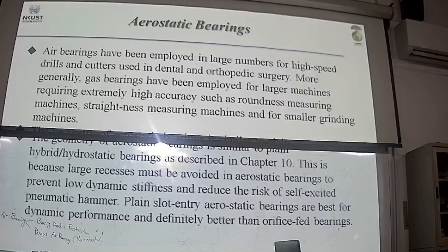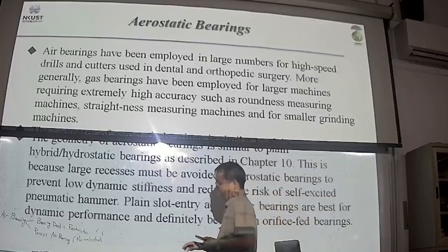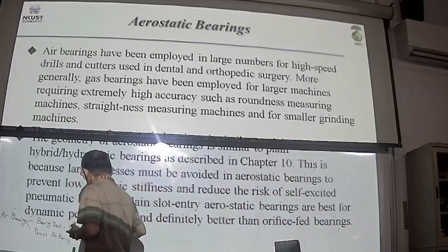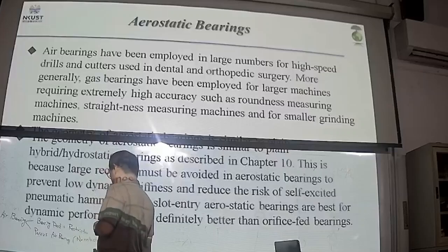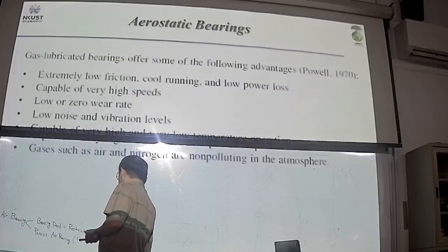And for the air bearing we discuss here, we always discuss the bearing pad design plus the restrictor design. And for this one, the supply pressure is usually smaller than 6 bar.